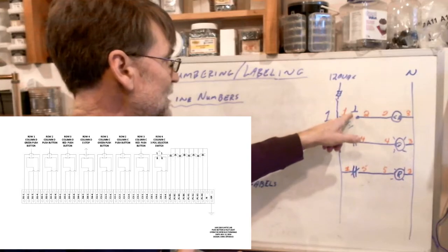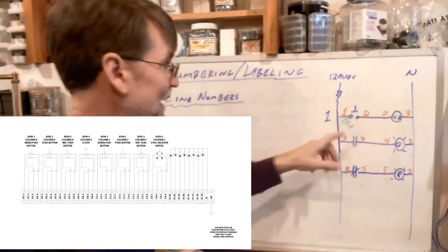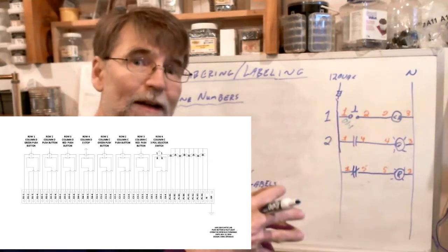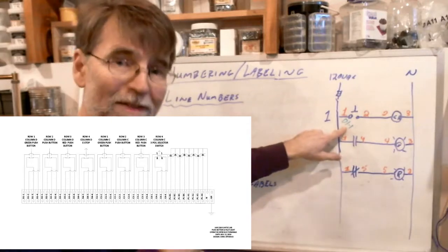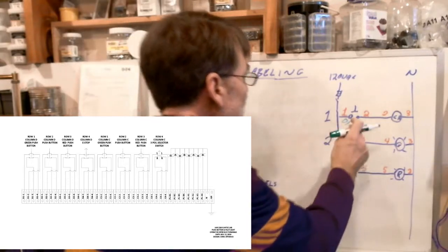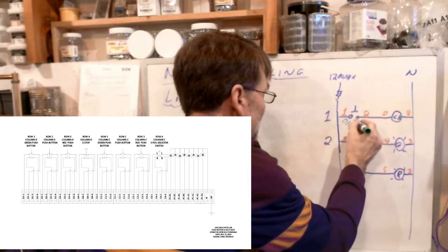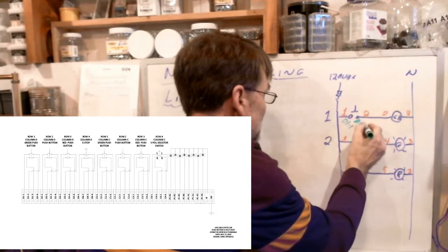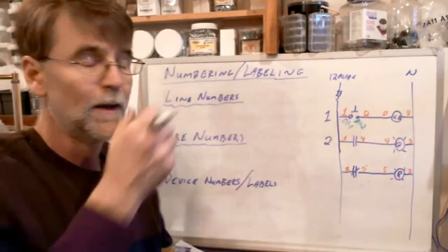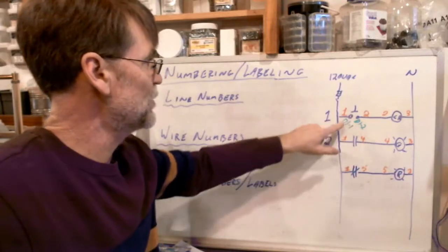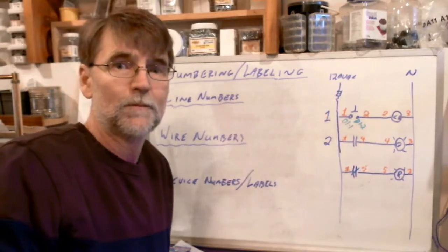That is a label on a terminal at your lab station. And this left-hand side of this push button is already pre-attached to this terminal with that label. And the other side of that same push button is connected to D12. So we have to put these labels on here so we know where wire number 1 goes.